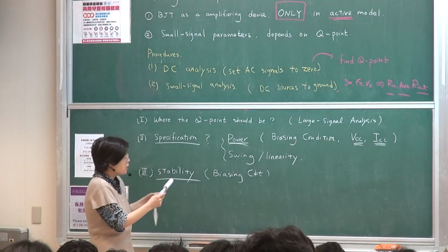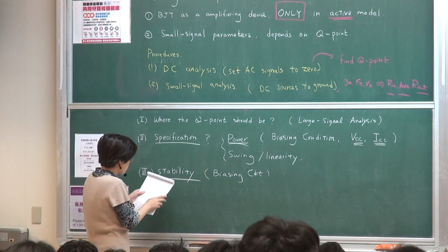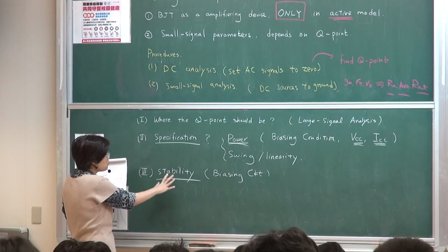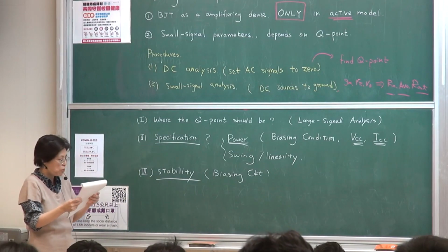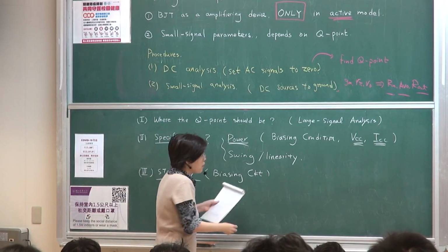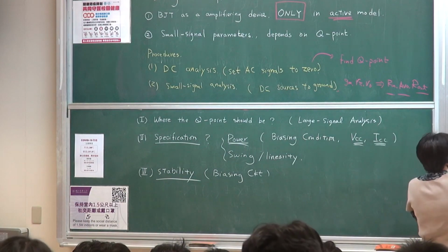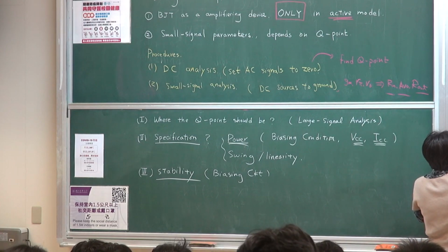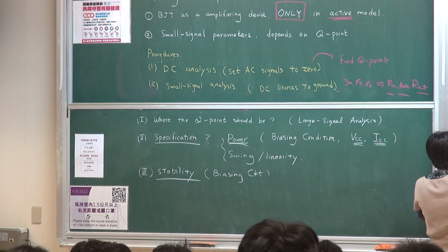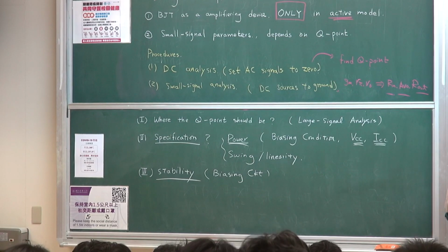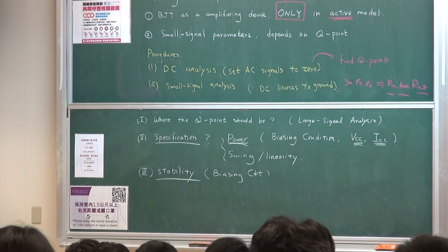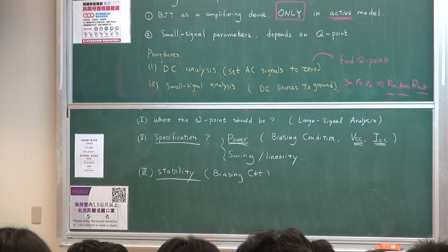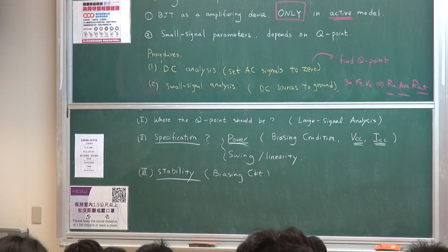As I said, we're going to go through a few of the biasing designs, and then we're going to talk about how you actually select your Q points. So let's say I just wanted to bias my circuit. For a biasing circuit, we start with a specific requirement, mostly to set IC or VC, a target value or target level.